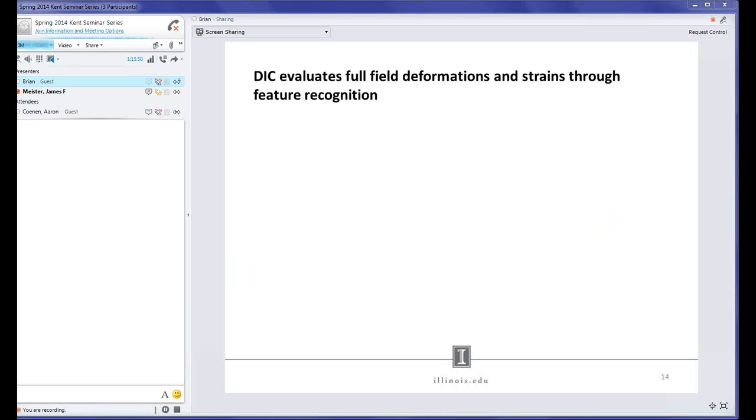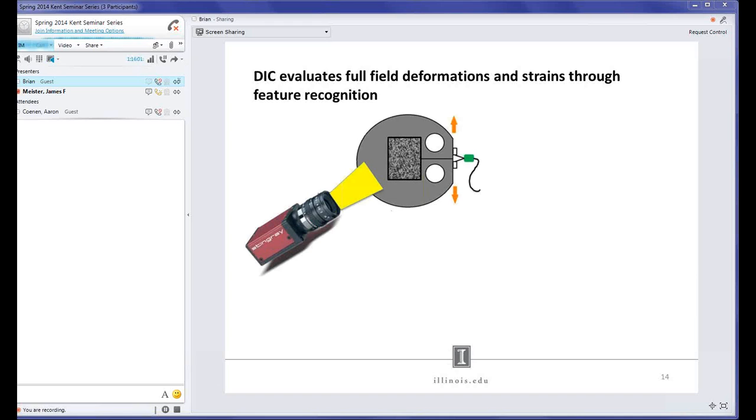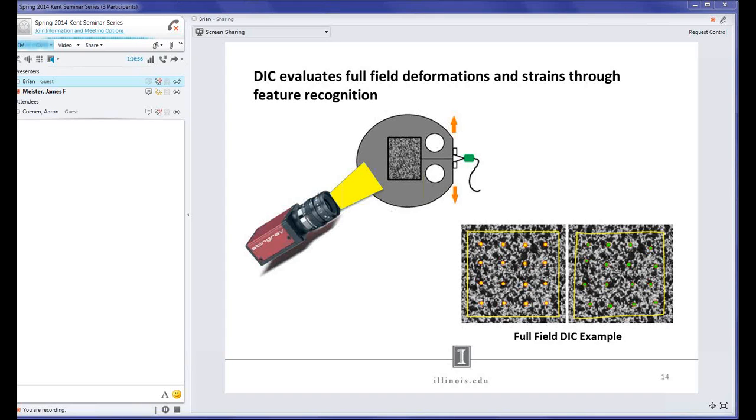In terms of the digital image correlation method, I'm not going to get into the crux of it like I did last year, because I think a lot of people have seen digital image correlation now. I could talk about it further in the question and answer. Right now we're focusing on using CCD cameras, Stingray F201C, so that we can have higher speed image procurement. We do have a 21 megapixel camera that we use at times, but that's mainly for creep compliance, because the magnitude of the displacement field is much smaller in the creep test, so we need to be more resolute. But it's just too slow for us to use in a fracture test.